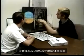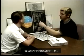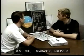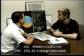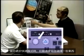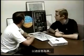And what this does is, it means I want to climb at a specific preset speed or descend at a specific preset speed. And that's going to appear as a managed speed in the speed window. During expedited climb, it's going to climb at green dot. Problem with green dot is that's really slow. Now, yeah, it's L over D, but we don't want to be getting down to 210, 220 knots. So an easier way is to do an open climb at about 250, 240. You can figure it out, you're a big guy. The expedited descent then references 0.80 or 340 knots. If you happen to, for whatever reason, while you're in an expedited mode, pull the speed knob and select something else, you're going to revert to either open climb or open descent, whichever is appropriate.